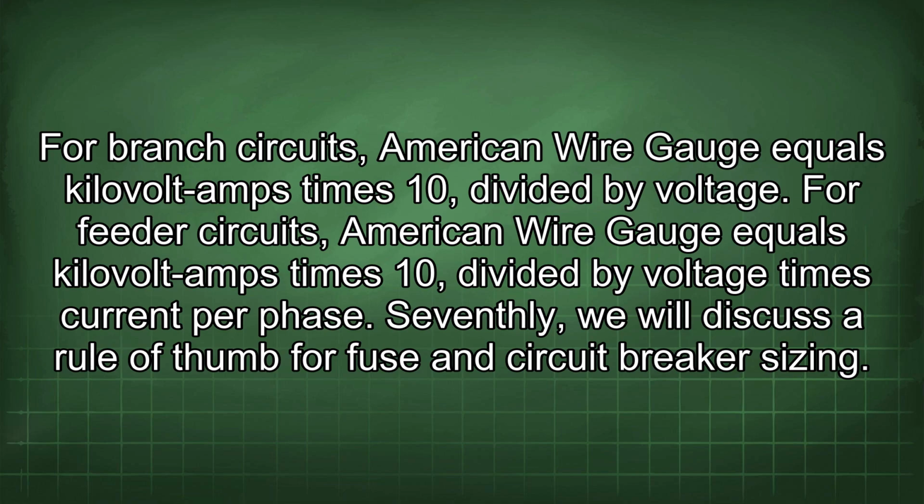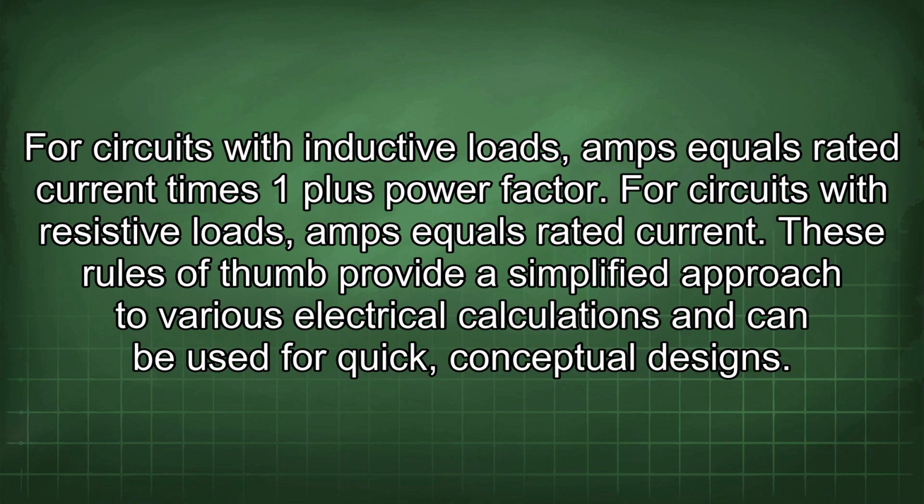Seventhly, we will discuss a rule of thumb for fuse and circuit breaker sizing. For circuits with inductive loads, amps equals rated current times 1 plus power factor. For circuits with resistive loads, amps equals rated current.